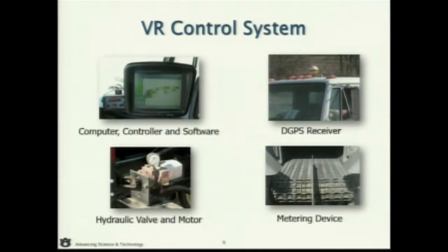It's an apron chain, and the speed of that chain is going to drive what the actual application rate will be. So we load our map in the top left. We have our GPS. We know where we are at any point in that field, and we're going to apply what that map says. And the hydraulic motor is going to do all the control aspects, or the speed of that chain.